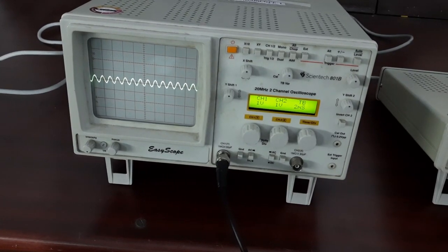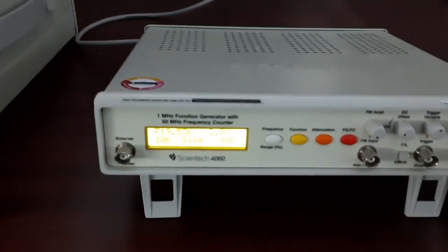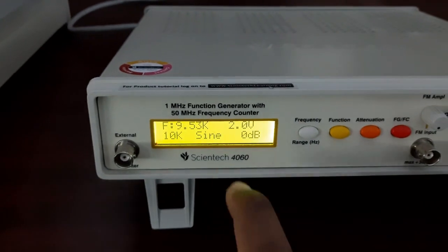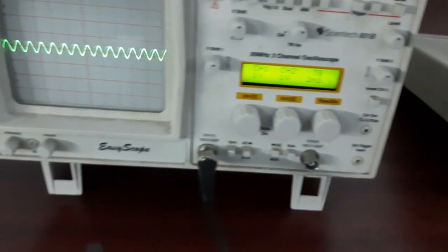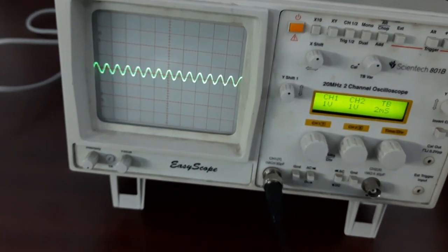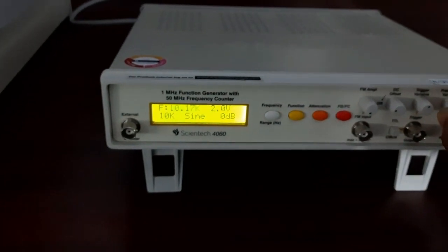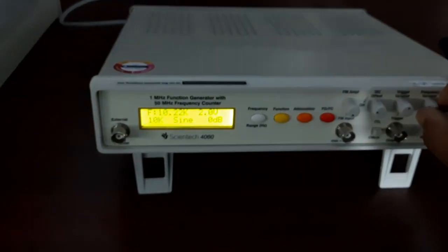As you can see, after the cutoff frequency, the output of the high pass filter will be shown on the CRO. Now the current frequency we are giving from the function generator is 9.53 kilohertz. So at 9.53 kilohertz, we can see there is output coming through the high pass filter, because it's a high frequency wave. Now you can see 10K also it is giving us values. On 10K it is also high frequency.